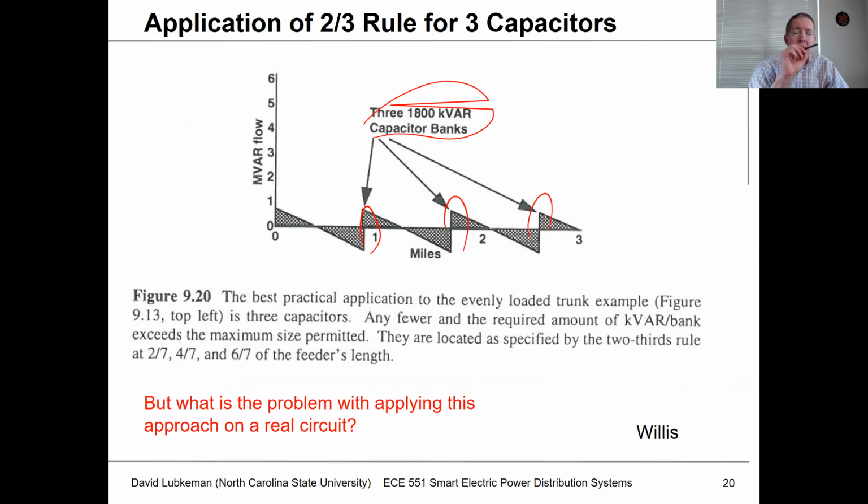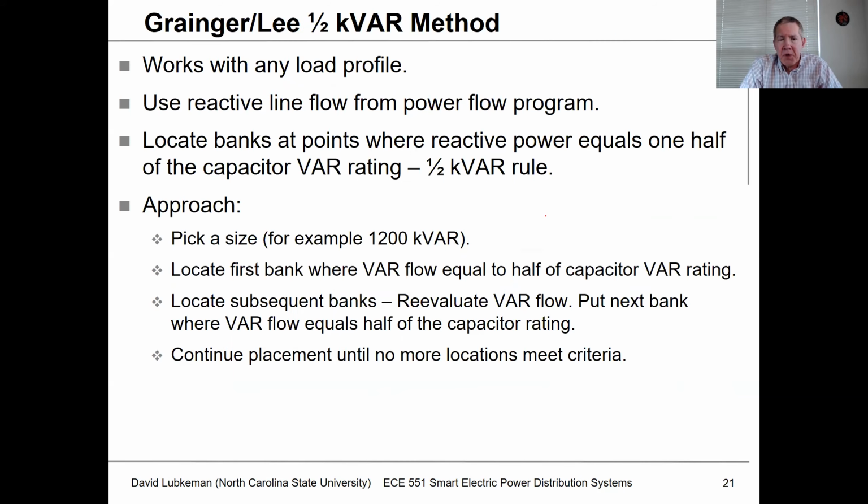But again, the problem you run into is for a real circuit, it'd be hard to get these capacitor sizes and have availability to these locations. And so as I mentioned before, what we would actually be using in a realistic circuit, if I were looking at multiple capacitors, is this half kVAR rule, which we'll get into in the next video segment.